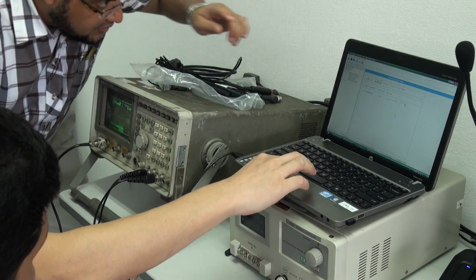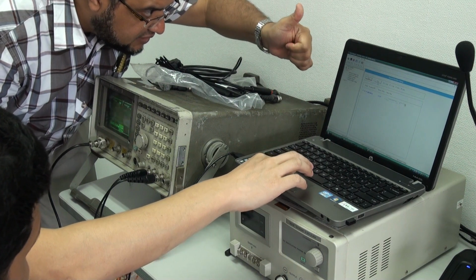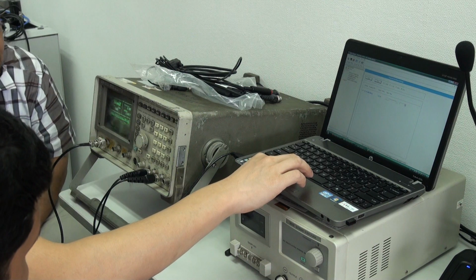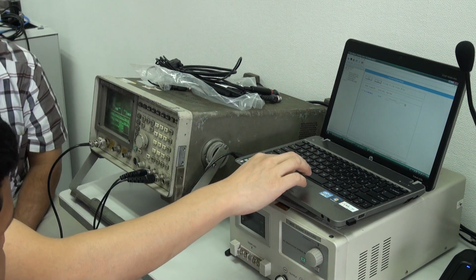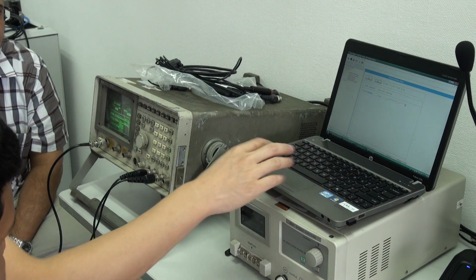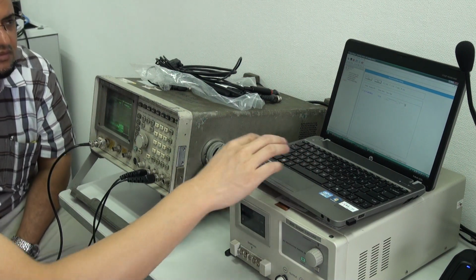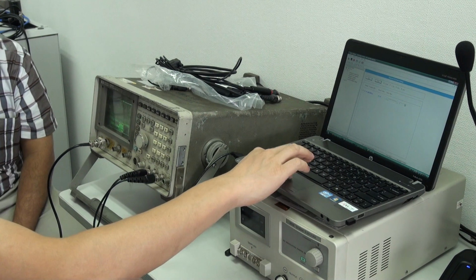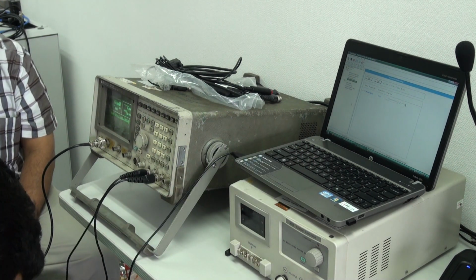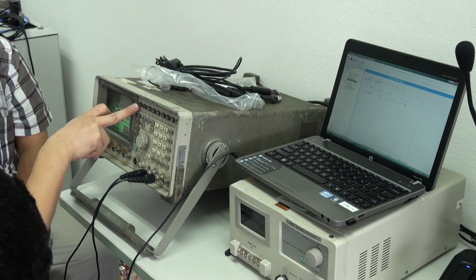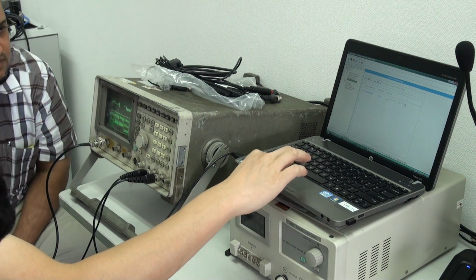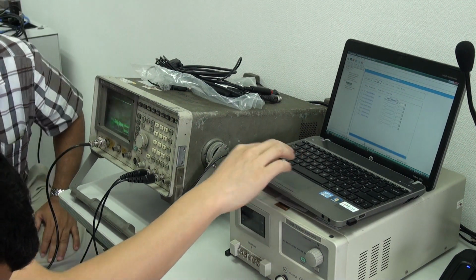The important things are reference oscillator, transmit power, and deviation. That's it. Usually speaking, for the TX side, we just do the first one, the second one, and the third one, deviation. It's okay. Save. And then we go to the RX side. Okay, RX side. And then the first one is the front end filter.